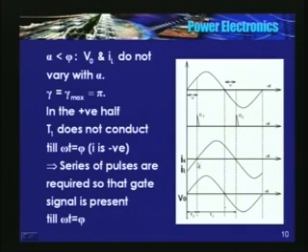Okay. So even if you have triggered T1, it will not carry the current, or current will not flow through it, because current is negative. See here, current is negative only until it cuts the x-axis. This current starts flowing through T1, and this instant is fixed by the power factor angle phi. So till phi current is negative, so even if you try to trigger T1, it will not carry the current. This current is being carried by T2.